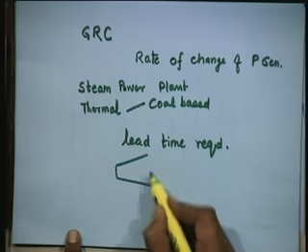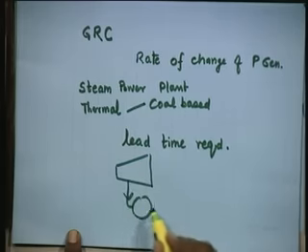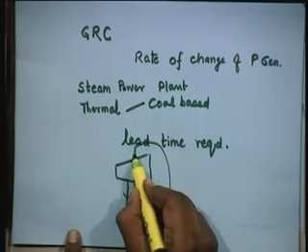The generation rate, from safety considerations of the equipment for reheat units, is quite low. Most of the reheat units have a generation rate around 3% per minute. What is a reheat unit? There you have a turbine, I have explained earlier also. You take out steam, pass it through a reheater and bring it back.